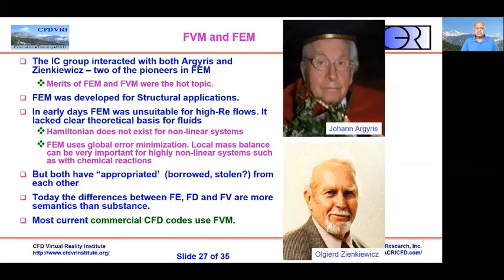Finite element was initially developed for structural applications. It was based upon a minimization of the Hamiltonian, and it worked for that reason, that you could seek the minimum energy of a system. In early days, finite element was unsuitable for high Reynolds number flows. There was no clear theoretical basis because a Hamiltonian doesn't exist for nonlinear systems.